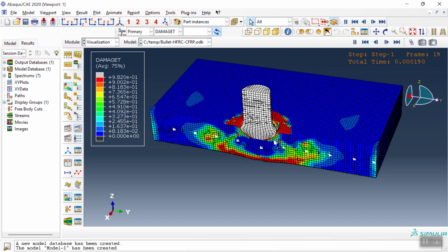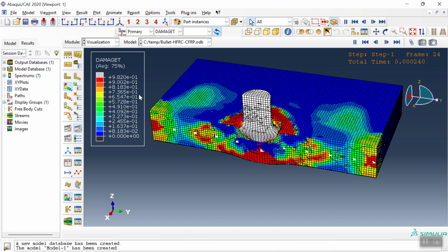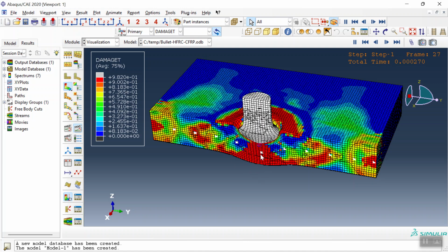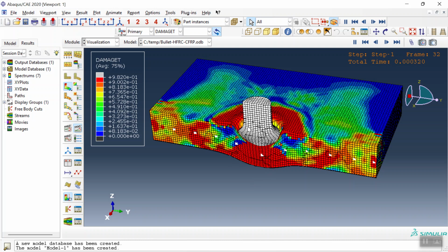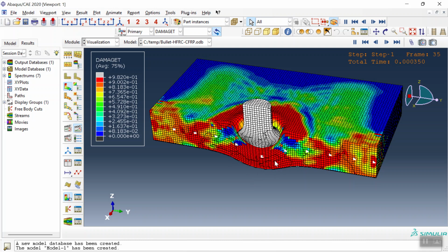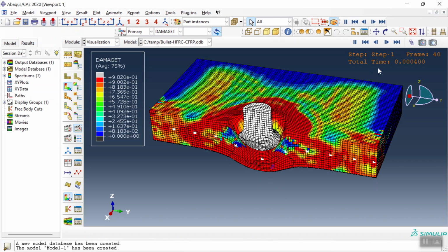Under the penetration, this panel is fully filled because the maximum damage happened. And if we use strain damage as a sub-option in the model, you will have element removal here, and this element would be removed from the model after the impact.